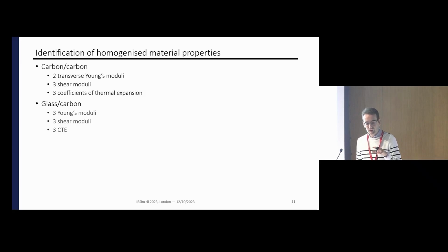That's why we need to fix one of them. And the most relevant to fix is the longitudinal modulus of the material, the better we know it the better. So it is the one which can be easily measured in another way. That's why we don't identify this Young's modulus, the longitudinal modulus for carbon. So I will not put much emphasis on the result of this identification. I prefer to talk about the methodology.